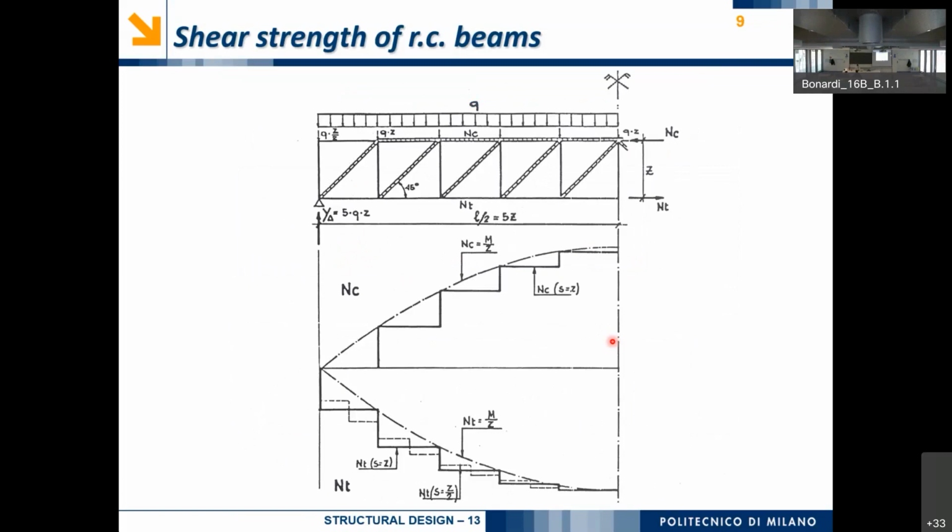So, if everything so far is clear, and we are at a good point of this topic, let's see how this lattice structure can be associated with our reinforced concrete beam. Well, basically, we have considered a generic beam with a generic distributed load. We don't care about it. If we consider an equivalent lattice structure that is equivalent to our reinforced concrete beam, we can see that we have an upper chord that is working under compression, and the resistant force at this cross section is NC, and there will also be a resultant tensile force at the bottom tie.